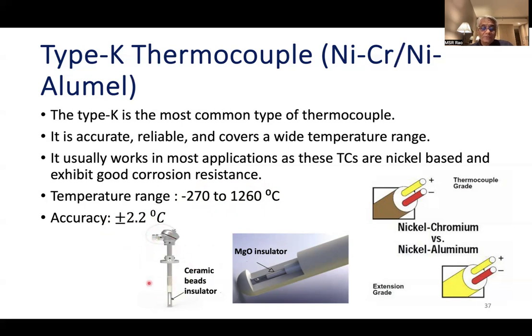So typically, a thermocouple looks like this, and this part is outside the furnace or the measuring space, and this is sitting inside the hot zone, which is also insulated. What you normally see is just two leads which you connect to the voltmeter. This part goes and sits inside the furnace, and on the other side you just connect these positive and negative terminals to the voltmeter.